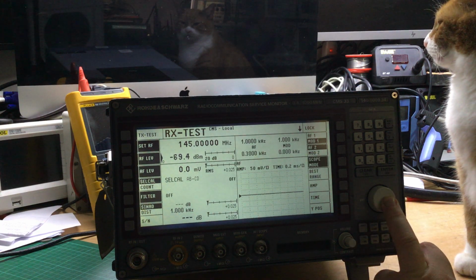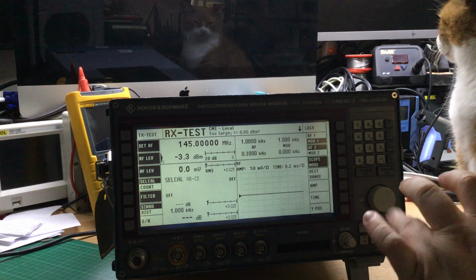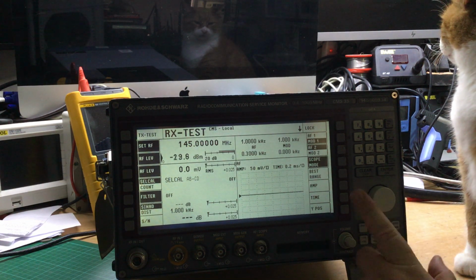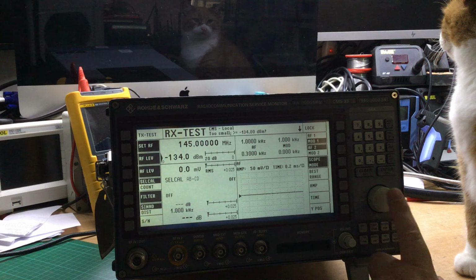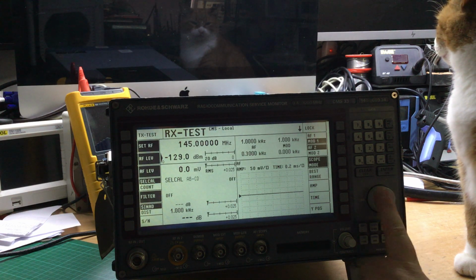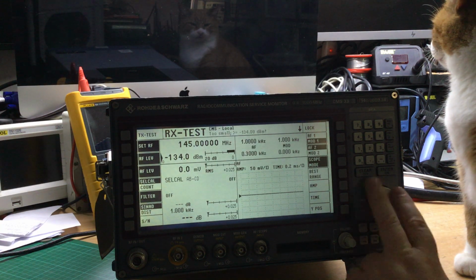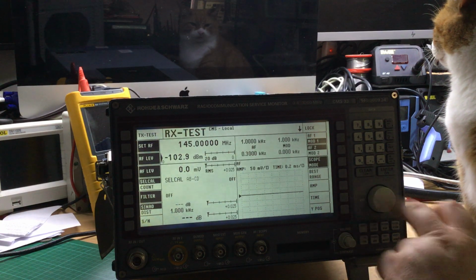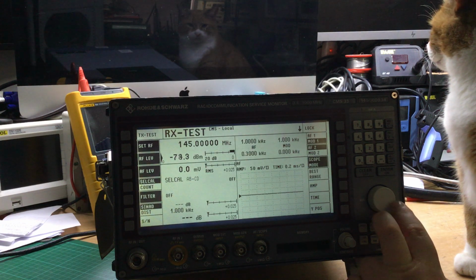I think that's an optical control that's got a decade output on it, pulses high or low depending on which way you turn it, but I'll have to look at the service manual on that because I'm not 100% certain. I know the Marconi radio test sets, it's an optical encoder. I don't think it's a binary coded decimal switch control with any data outputs on it, but I could be wrong. We'll just have to look in the manual. But if you spin it really quick like that, sometimes it sort of sorts itself out, it cleans itself up if you like, and then starts behaving itself.